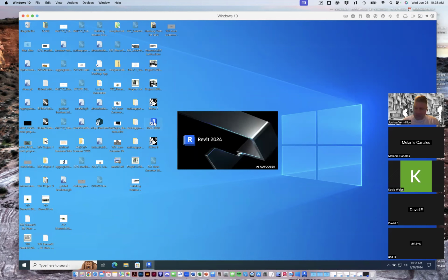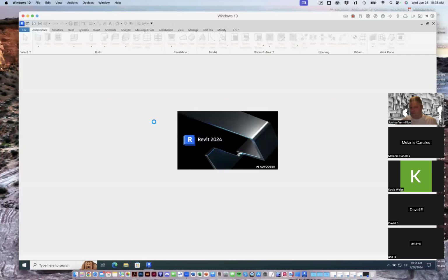But again, anytime I'm adding, first of all, with curtain walls, if you want a window wall, you add that as a wall type, as a curtain wall or storefront, like I just did. If you just want to insert a window into an opaque wall, then that's where you use the window component. Right? So let's see here, the window family, if you will.